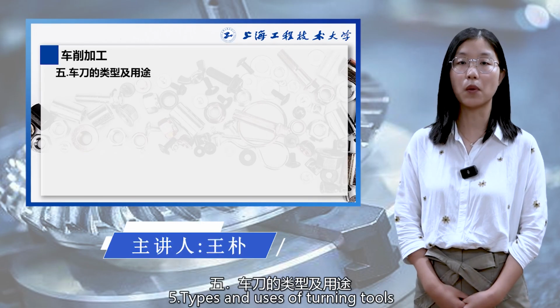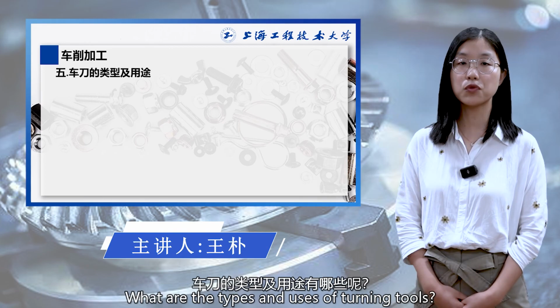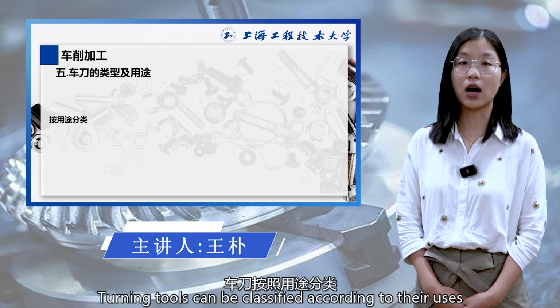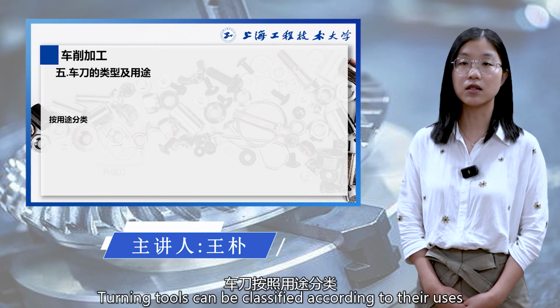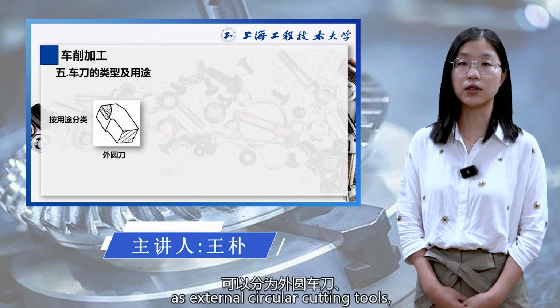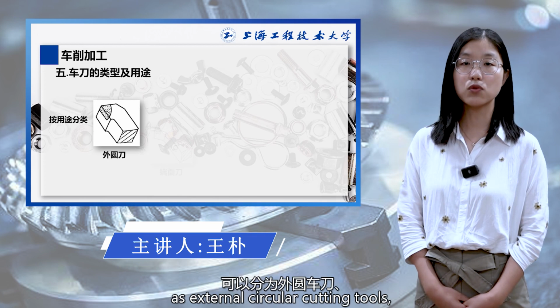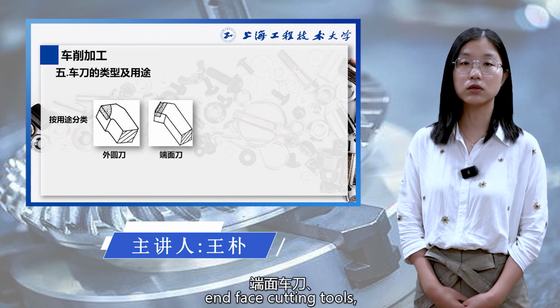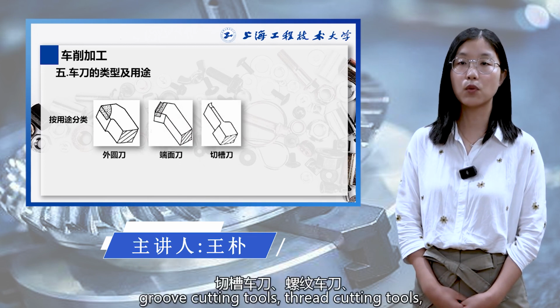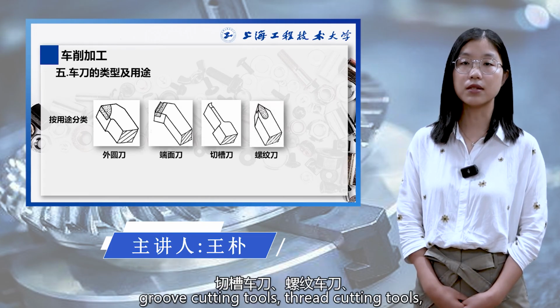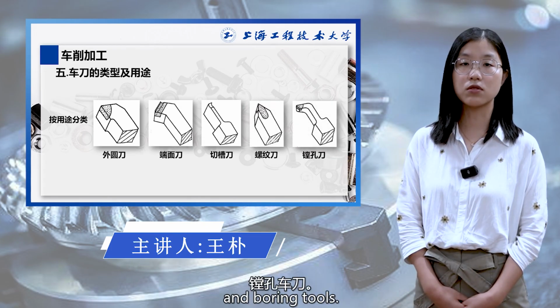Fifth, types and uses of turning tools. What are the types and uses of turning tools? Turning tools can be classified according to their uses as external circular cutting tools, end face cutting tools, groove cutting tools, thread cutting tools, and boring tools.